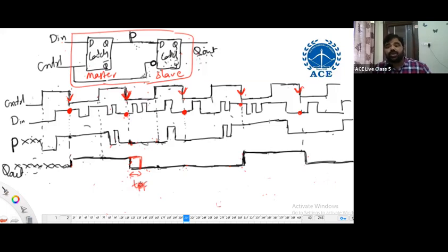The time required to change the flip-flop output from inputs changed will be wrong. It is not from input to output change. What is it here? It should be considered from the clock edge occurrence to Q output variation. So it is named as TCK to Q, clock to Q delay. From the clock edge occurrence, it is taking some time to change the output.